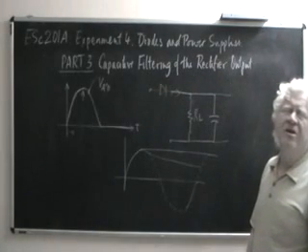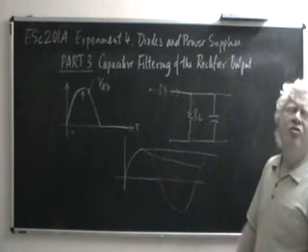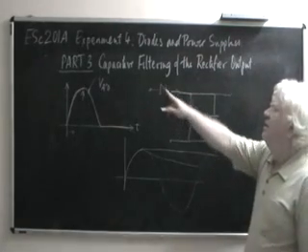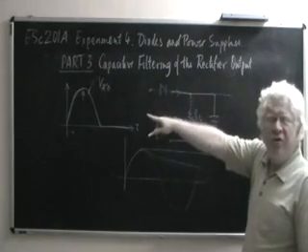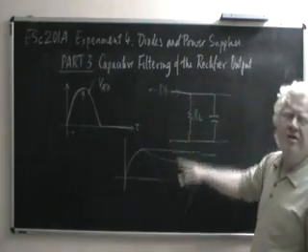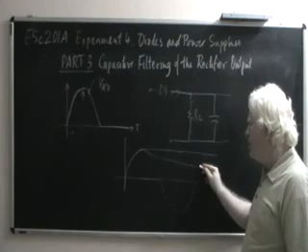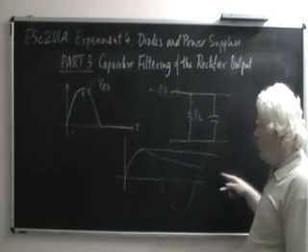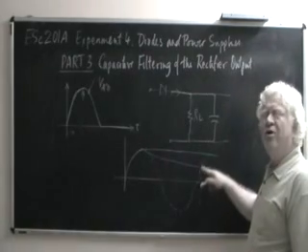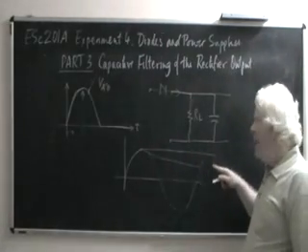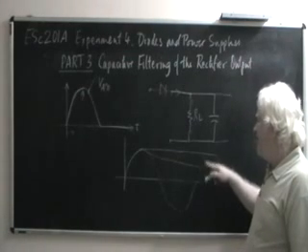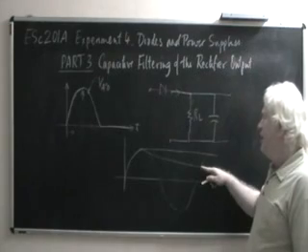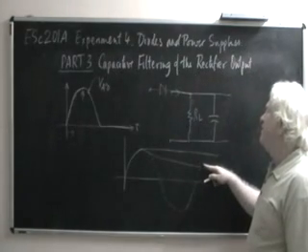How long does it continue to fall? It continues to fall until the time when the rectifier input side produces a voltage which exceeds its voltage at that point of time. So you have an exponential curve going down at this point, and you have a sinusoidal curve going up. And at that instant of time when the rectifier input voltage exceeds the capacitor output voltage,